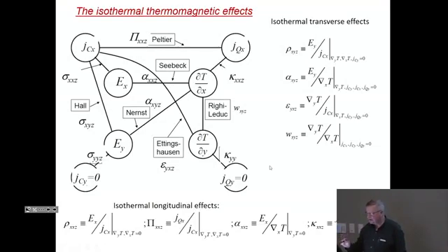So let's repeat once again. The relation between current and electric field is the resistivity if you keep everything else constant, so if you're isothermal. The relation between heat flux and temperature gradient is the thermal conductivity if you don't draw current out of the sample. The relation between the transverse and the longitudinal temperature gradient is the Righi-Leduc effect, assuming, of course, that you draw no current out of the sample anywhere. So these little conditions are important.